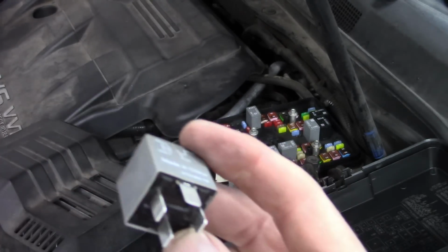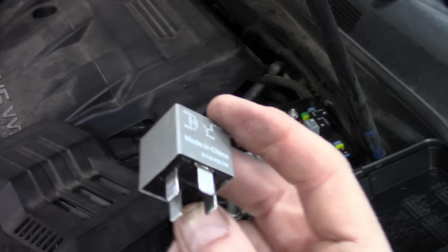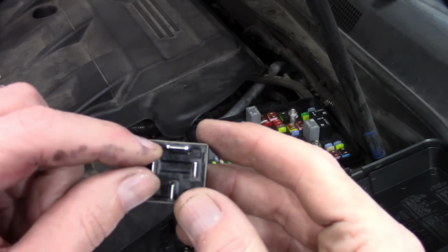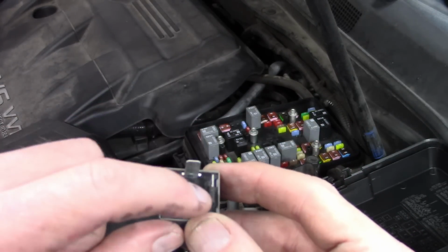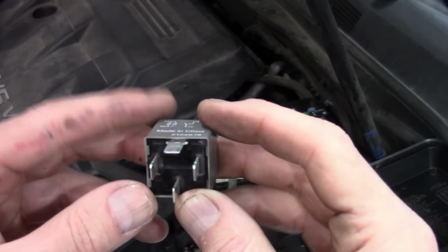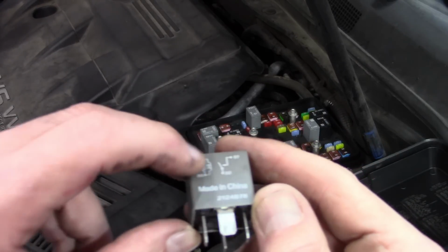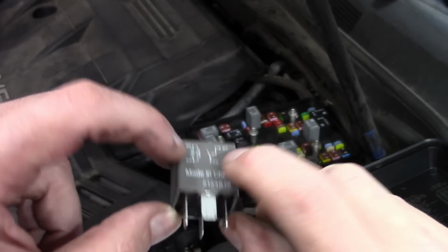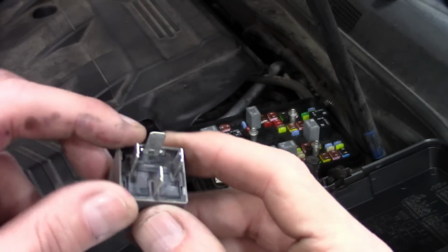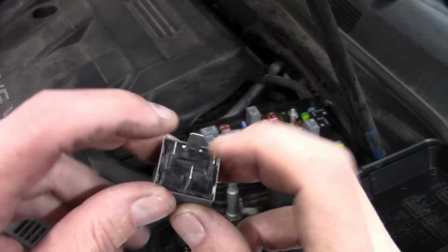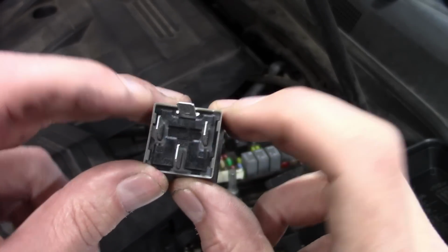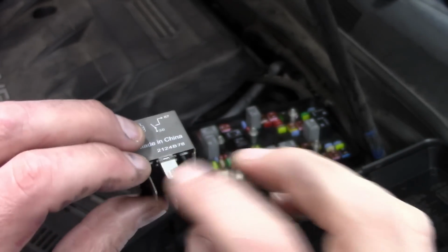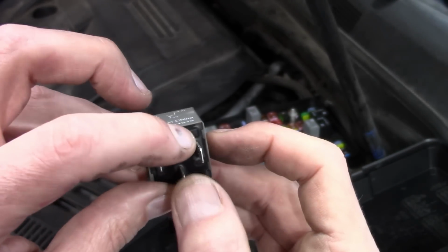Here's another thing I can do to cheat just a little bit. If we look really carefully, our control side terminals are not as thick and wide as our load side. That's because you use less current on your electromagnet. On your control side, you use low current to control a higher current circuit when we close that switch. So we can just look at the relay and I can tell you that these points here, 85 and 86, are definitely thinner and less wide than our 30 and 87. So these are definitely load side.